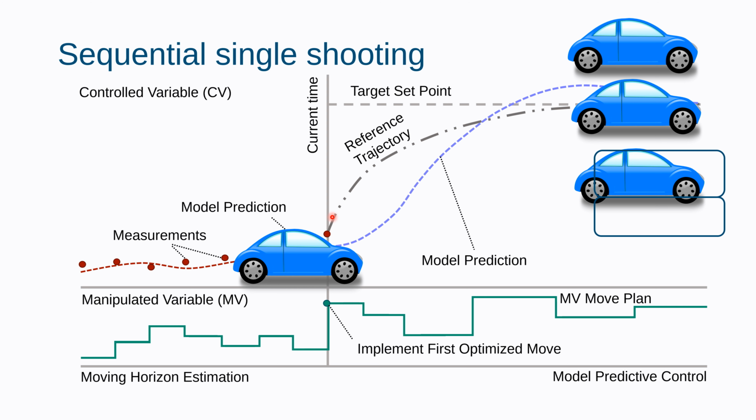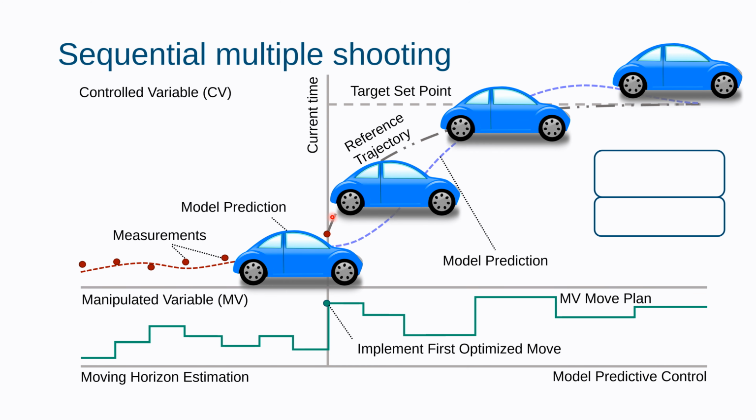The objective function is how close you're getting to the target set point. So you do that over and over again, minimizing maybe a sum of squared errors between your trajectory, CV sub t, and the predicted CV value, with the reflux ratio between 0 and 100, let's say, subject to the dynamic equations.